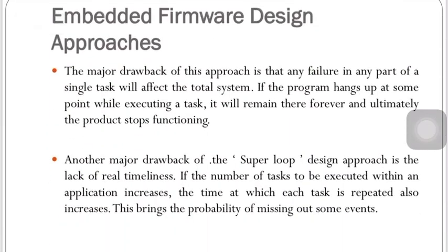Now what are the drawbacks of this super loop approach? The major drawback is that a failure in any part of a single task will affect the total system, because tasks are executed one by one. If any one task fails, it will stop there and damage the whole execution. Or if the program hangs at a particular point, it will be there forever and the embedded system will stop functioning.